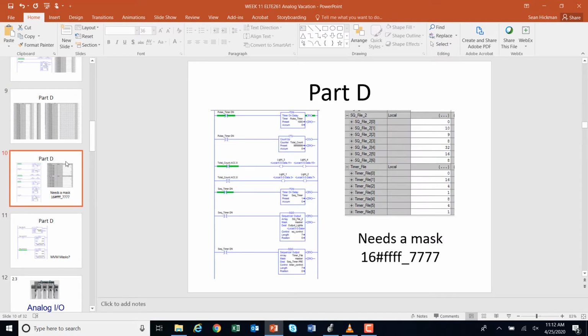The other way that you could have done this was you just could have had two sequencers. So the first sequencer right here did just what we wanted to. Here's the 10 again, so it pushed the 10 out. But what is cool is the second sequencer here is the number of times that 10 gets pushed out. We put 16 in here for that timer, and so that timer times for 16, and then this sequencer advances to the new position 9,